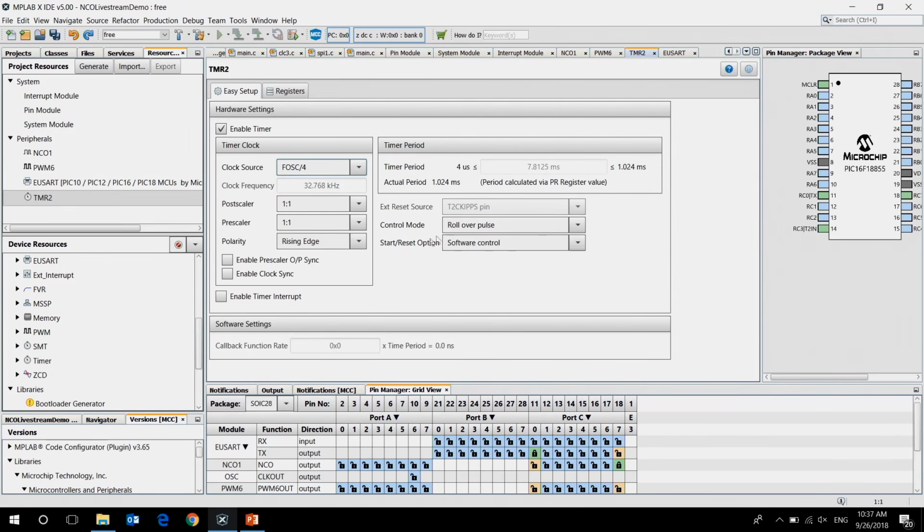So if you look at my monitor right now, I'm configuring the PWM. And first thing you need to do is configure your timer resource here. And it's really easy here. If you change the prescaler, MCC is going to calculate the upper limit and lower limit of your period here. And you can put anything you want within that period. It's going to calculate the actual period here. If you cannot see it, it says 9.9 instead of 10 because of the resolution of your clock and everything. And your duty cycle is?